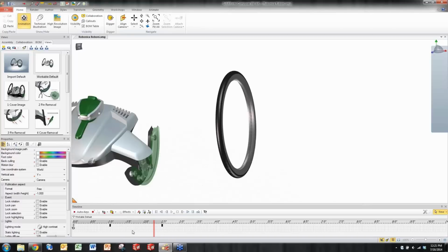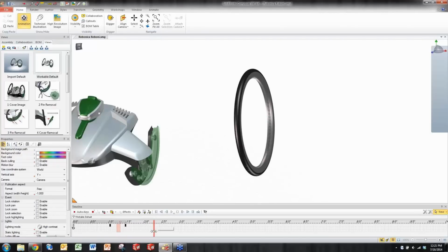If I have multiple keys behind, so maybe I should have left those opacities, I can basically put a bounding box here, and I get this little arrow at the top. If I drag this, it moves every key behind this arrow inward. So it's basically reducing and eliminating time. So it's another method of kind of reducing space between keys. So that was kind of like the brief tutorial of how to set keys.